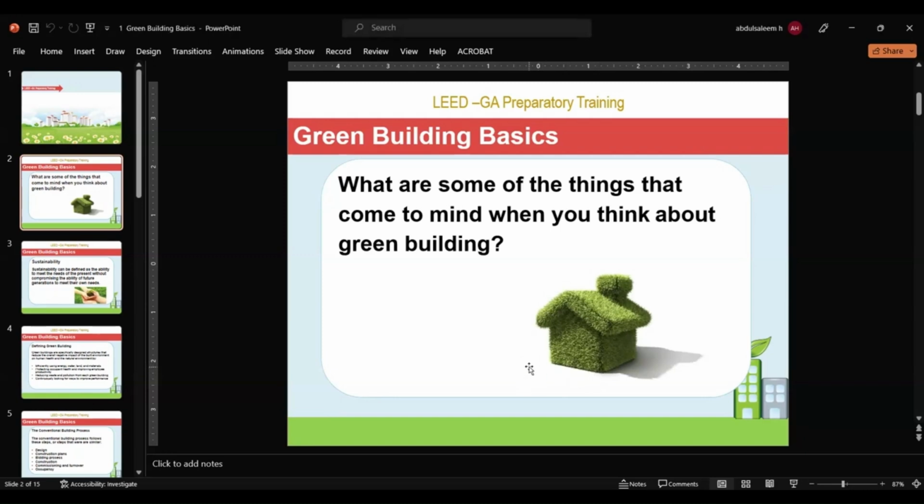When the building has those types of practices, you can apply even in the operation and maintenance stage for rating the building and get the green building certificate. When they apply for LEED, the auditor, like a LEED AP for O&M, will come and check the rating based on the practices. They give points for each standard, sum up the total points, and check whether the points are above 50. They will give a silver rating or gold rating based on that. In that way, each building at a different stage can get this certificate.